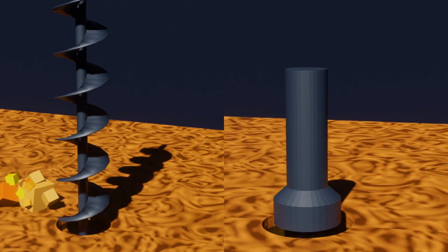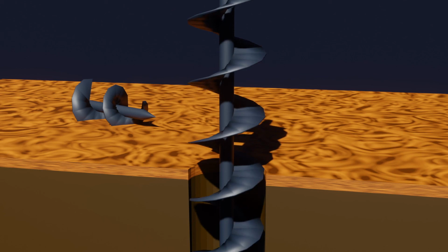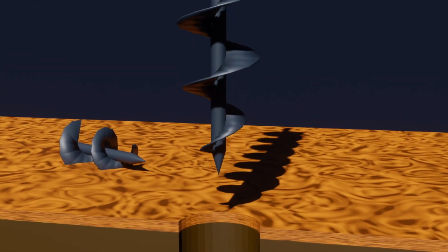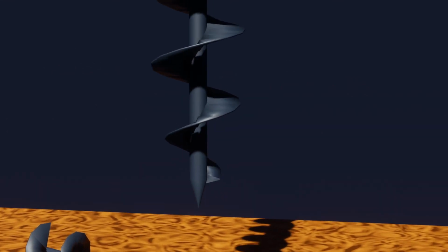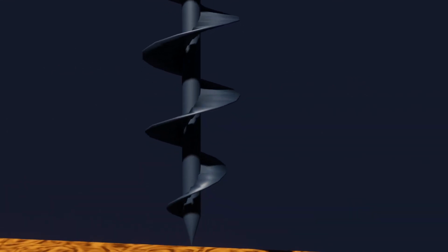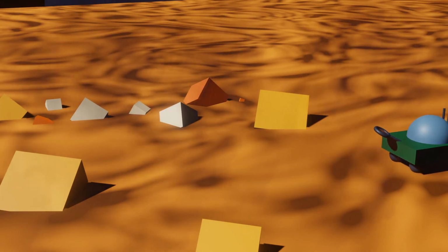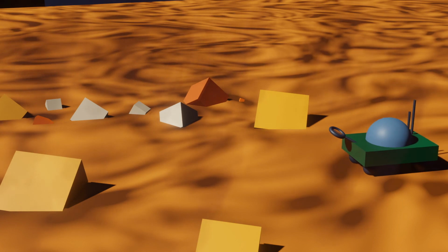Generally, planetary drills are most often rotary drills that use a helical auger. Although this is not the most efficient method regarding power efficiency, and in spite of problems posed by bit dulling and autonomous drill string assembly, this method is favored because of the substantial amount of knowledge and experience connected to it. This poses problems as on Mars, rotary drills are not assessed to be the most reliable option.